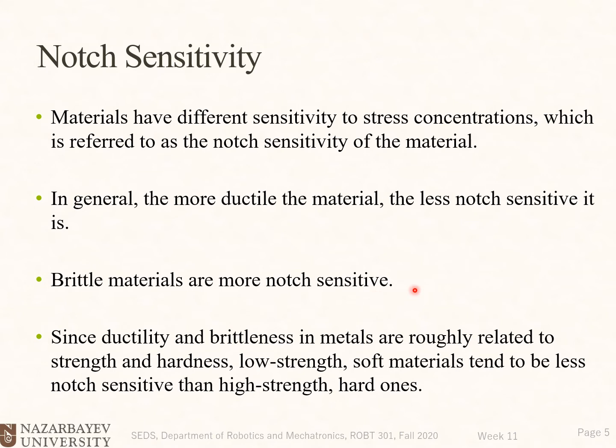Okay, so anyway, you see that for static cases, we could ignore stress concentration in ductile materials. But here we have to consider the effect of the material for both of the cases, and we see that anyway ductile materials are less notch sensitive.